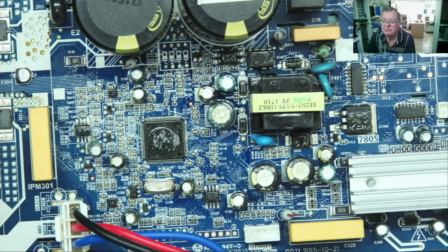It could be corrupted due to user error. For example, people trying to flash a device, update a BIOS, something like that, and they put the wrong firmware in, or something happens during the update where the power goes off, you have a power cut, things like this, and you can easily enough end up in the situation where the thing will no longer work. This can be very difficult or impossible to repair, because there's no point replacing the component with a new blank one, because it's not the component itself that's faulty.